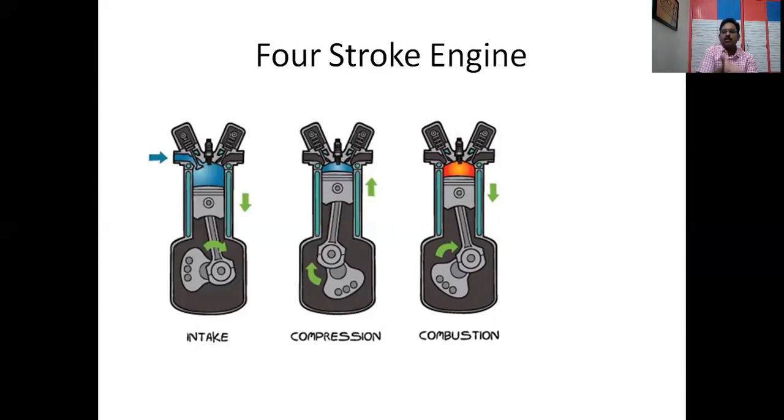So earlier we were only moving that one. Now here the thrust is pressing down the piston. So this is where the real power will be generated, in this stroke. That's why the third stroke is also called the power stroke, expansion stroke because the gases will be expanded, and combustion stroke because combustion takes place and the power will be generated. That's why it is suitable to call this stroke a power stroke.